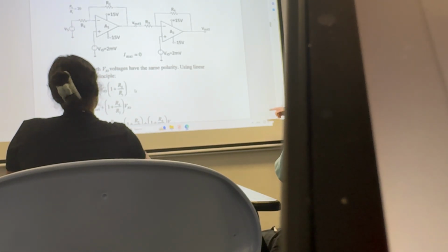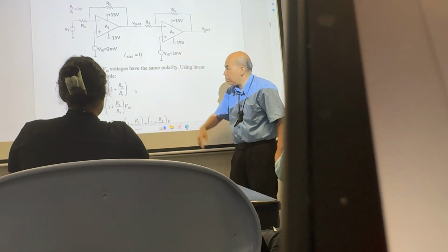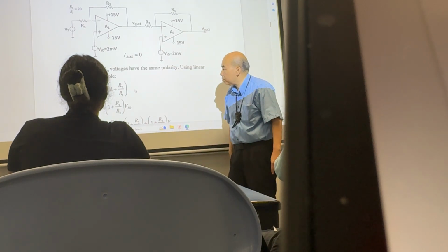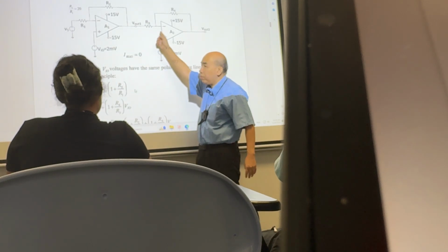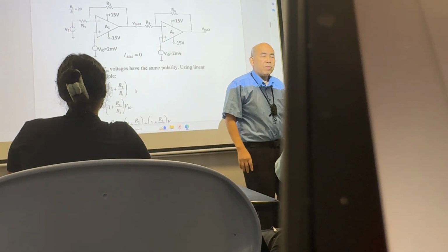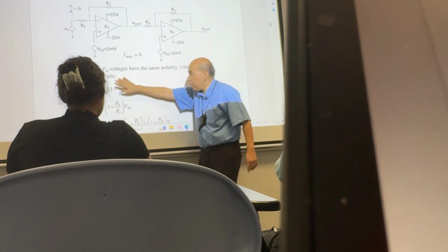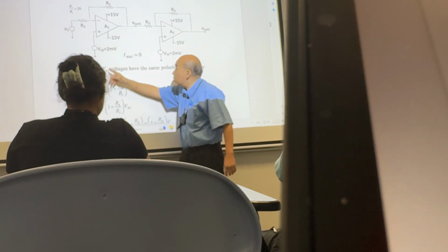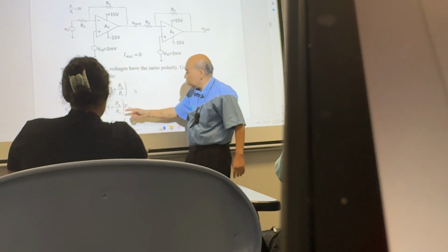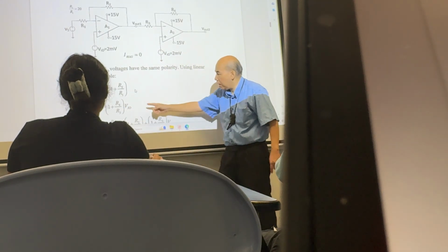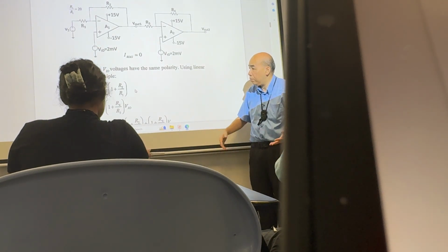Okay, now we compute the total output on VL1. This is an intermediate point. That is 2 components combined: you have signal and offset. Now you can see that it's not just a signal going in. You have an offset going into the input of the second stage, right? Treat these 2 components like a source, combined together. This source will be amplified by the inverting gain, but the offset here by the non-inverting gain for the second stage. Because the Vi naught for the 2 stages are identical, we write identical. They may not be the same, it may be VIO1, VIO2, right?